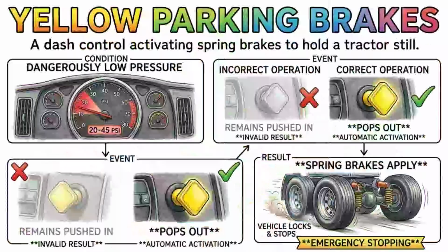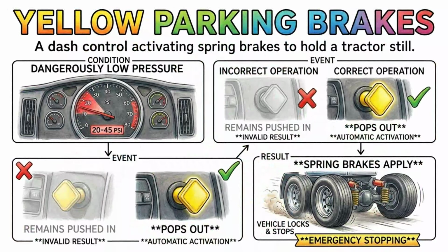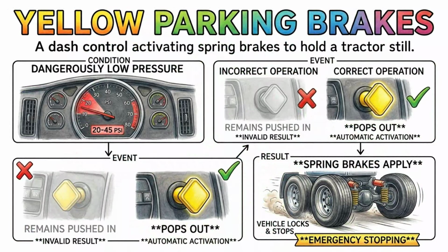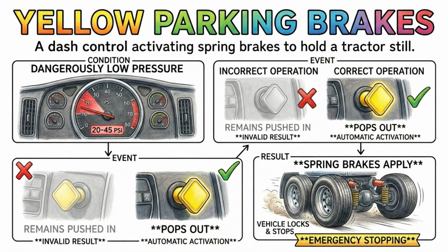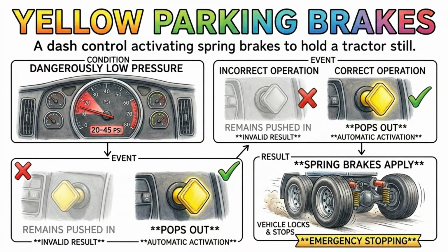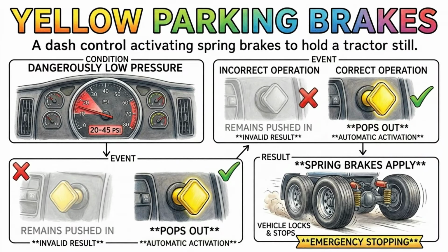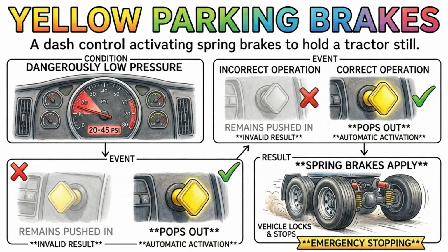To provide extra protection against ice forming in the system during harsh winter weather, some vehicles are equipped with an alcohol evaporator. This clever device automatically injects a fine mist of alcohol vapor into the air system. Alcohol has a much lower freezing point than water, so it helps keep any moisture in the lines from turning into solid ice. If your truck has an alcohol evaporator, you are responsible for checking the alcohol level daily and filling it up as needed during cold weather operations.